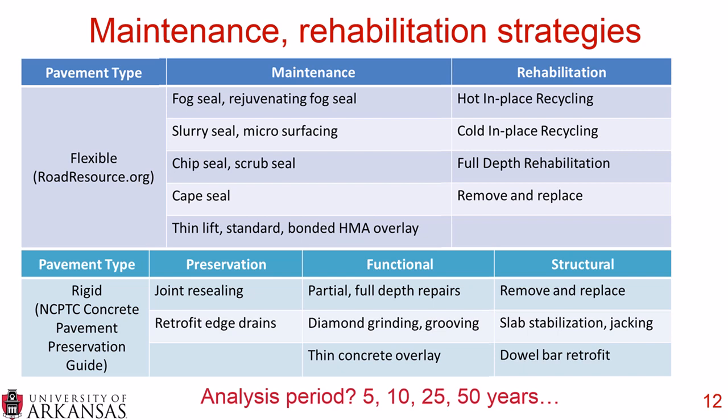Now, deciding what sort of maintenance or rehabilitation treatments, or preservation, functional, or structural treatments you'll apply, you need to consider your analysis period. An analysis period can be as long as you want. It can be as short as 5 years, and it can be as long as 50 years or even more. So it's really up to the person performing the analysis how many years in the future they want to look out.